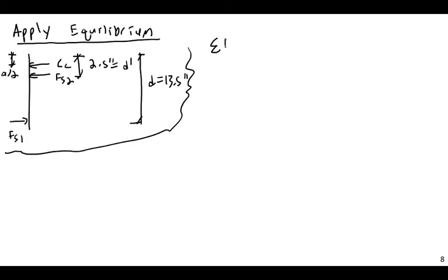First I'm going to do a sum of forces in the x direction is 0. Therefore, the compressive capacity of the concrete plus the equivalent force in the compressive steel, my FS2, minus FS1, must equal P sub N, the nominal axial capacity.